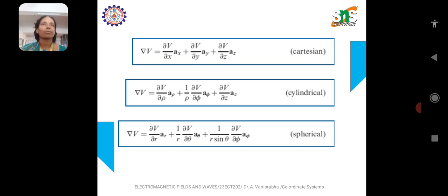The next is voltage with respect to the radial direction. If the element under consideration is a lengthy wire, the charge density associated with the entire conducting wire is rho L. Therefore, the voltage is equal to 1 by 4 pi epsilon naught times the line integral of rho L dl divided by the magnitude of r minus r dash.